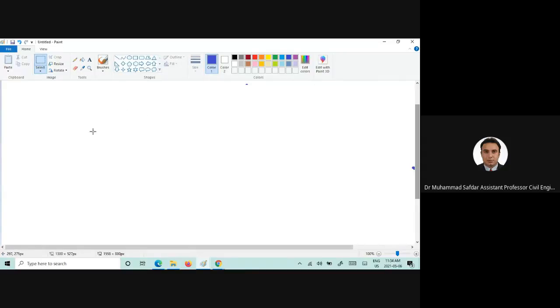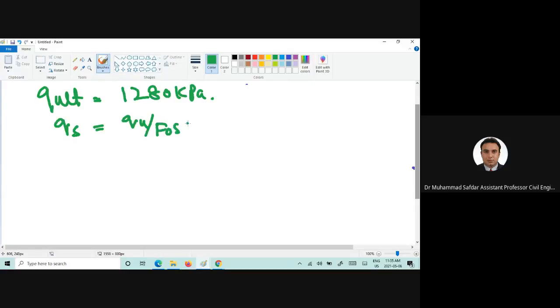and that is, now we are going to use the Q ultimate. So what was the Q ultimate value? 1280 kilopascal. And now what is the Q safe value, which is the Q ultimate divided by factor of safety? Please kindly give me this number. 255.9 kPa.